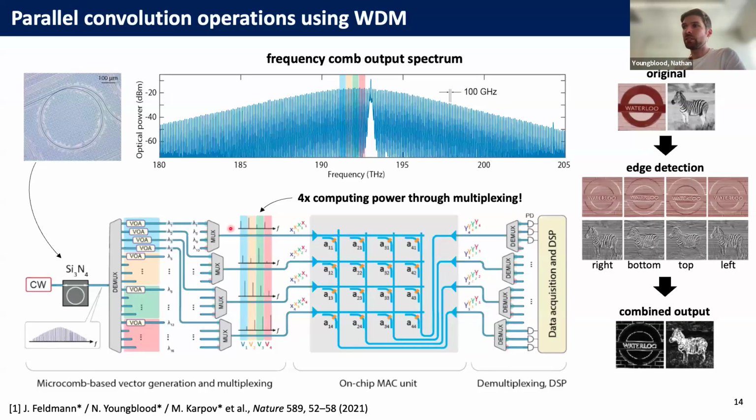And then you send those through the network, you would reduce the effects of beating in that case if you had some delays between the different lines, if the path length was not exactly matched. And in that case, you might be able to do a lot more within the same wavelength range, and you wouldn't have to worry about the interference. But then you suffer from relative intensity noise of those incoherent sources and stuff like that. So it's all kind of a trade-off, and it'd be interesting to look more into the incoherent light sources.